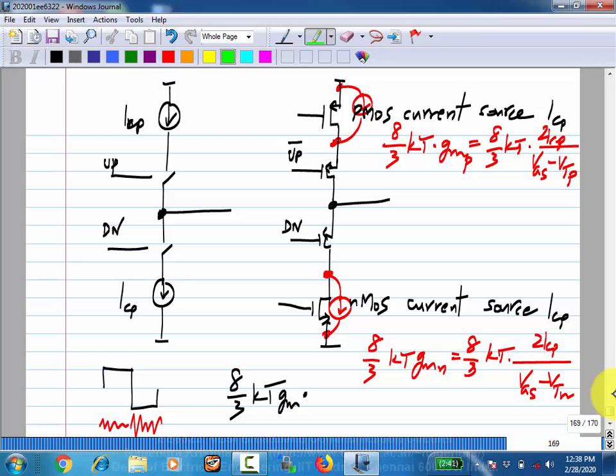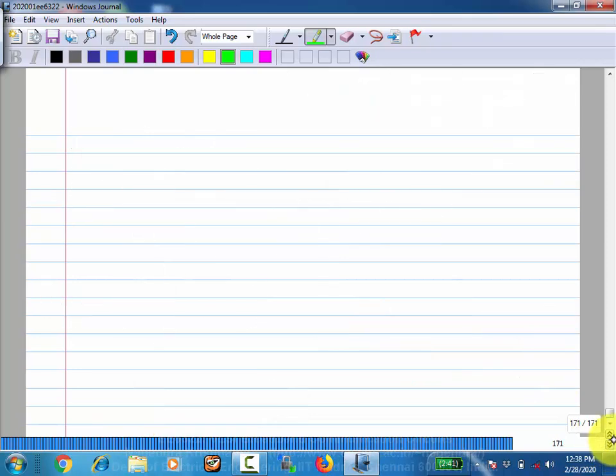Meaning, the combination of PMOS and NMOS is that, right? Well, you will have other control circuitry, right? If you want, I can put the switches here, if this is what you are looking for. So the switches don't have to be in series with the current source, right? So the upper current source should either pump ICP or 0. And one way to do that is, I can have a switch here.